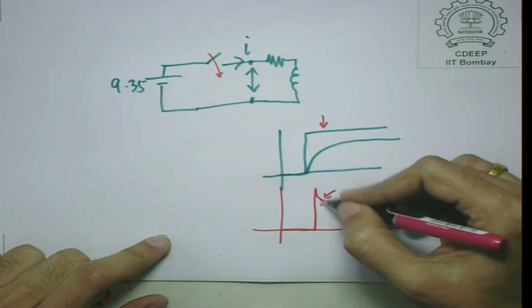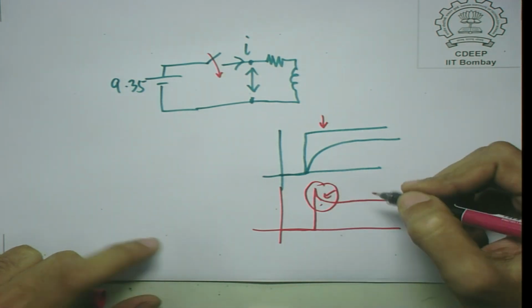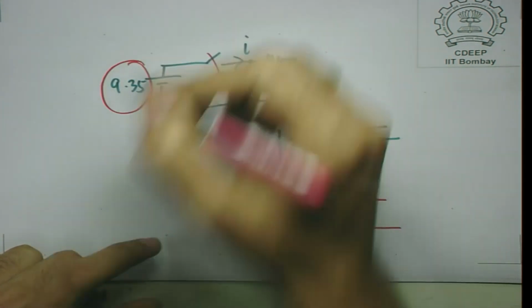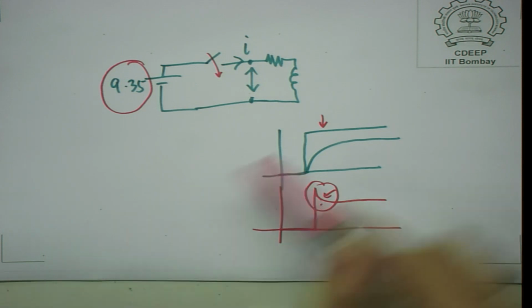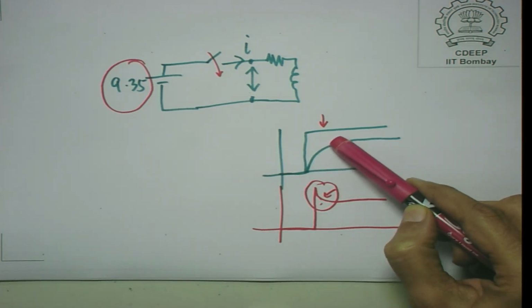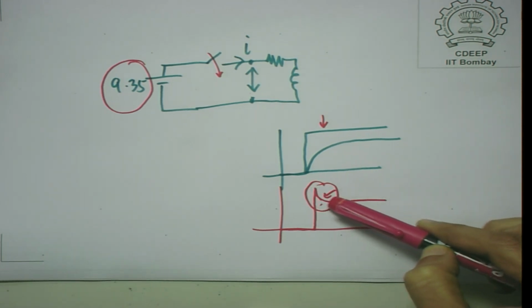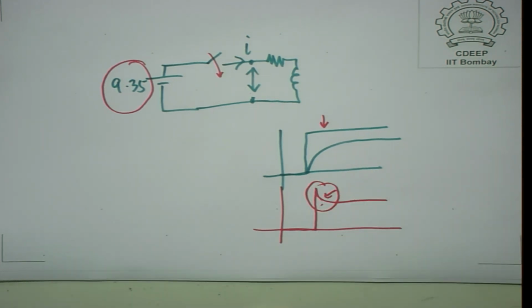So, this voltage waveform is not exactly a step, but you find the voltage slightly dipping, because this battery is again not an ideal source. When we draw more current from the battery, the voltage which we get across the battery actually decreases. As the current rises, the voltage drops. So, this really shows that this is not an ideal voltage source.